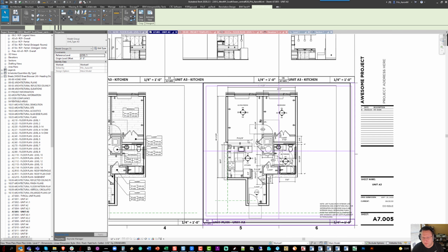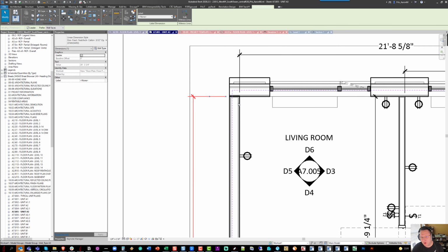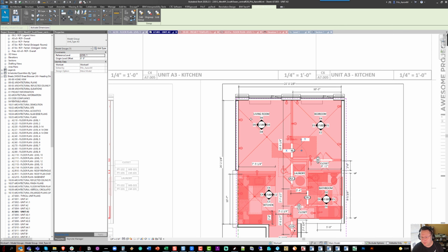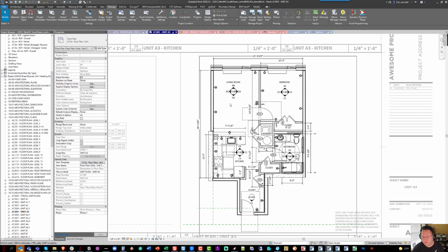And what I mean by that is if we jump into this floor plan right here and we look at some of these dimensions that we may want to harvest, of course, some of them are touching things like the exterior wall, which is not part of the group. We know that that means if I go to create an attached detail group and I try to attach these dimensions, it's not going to let that happen. But there are generally elements there in the group, such as finished floors or ceilings, or you could put in additional elements when you're doing the harvesting process that would allow you to then add in those detail items to the group. We'll do a quick sample here.